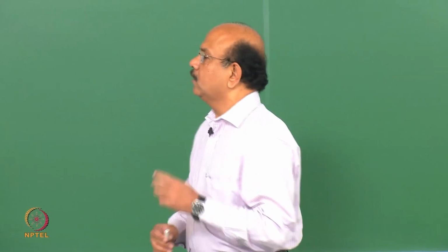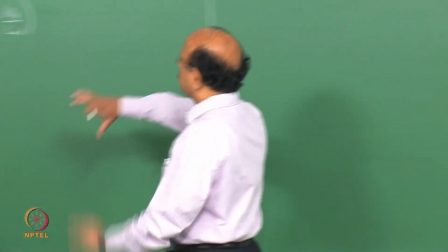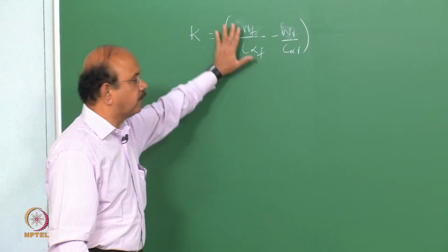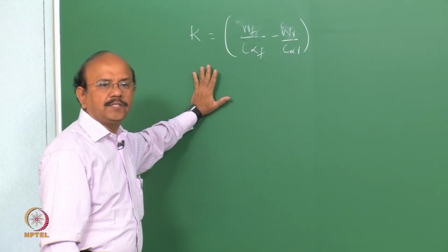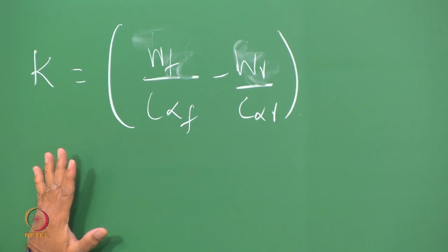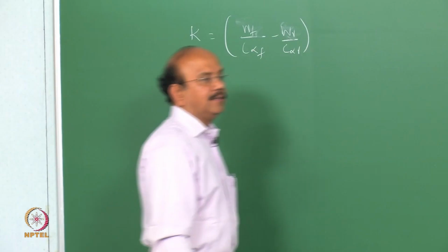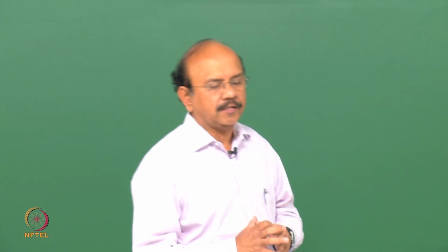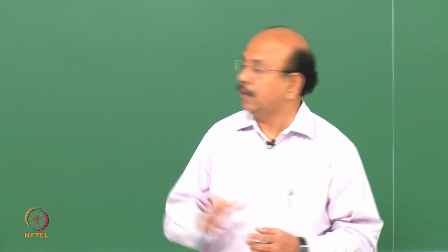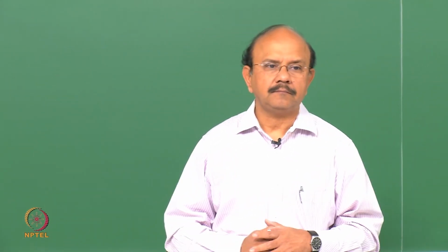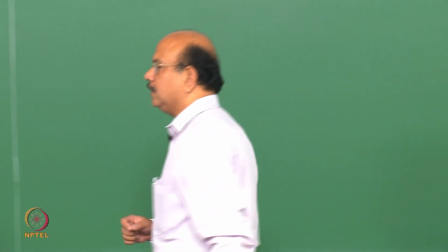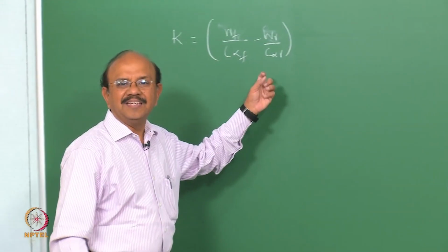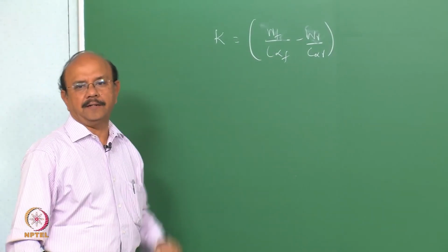What do we mean by expanding this topic? It's very clear that this is affected by the weights that act on the front and the rear. There are other things that happen in the car which are going to affect this WF and WR, as well as the assumptions that we have made regarding the linear behavior of the tire.